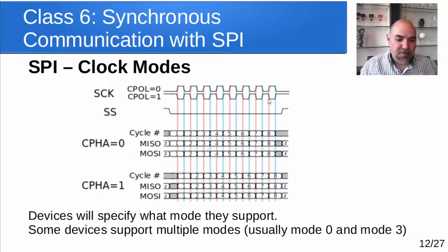All right, devices and their data sheets will usually specify what mode they support, or they'll have a diagram that shows the waveform, and you can deduce from that what mode it is. Some devices will support multiple modes, like they'll say compatible with mode 0 and 3.